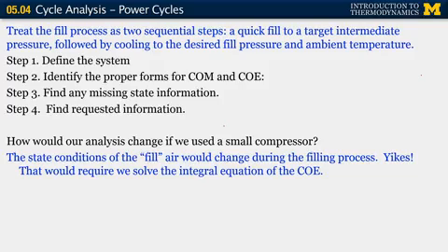Well, as we saw before, this transient analysis is pretty complex when we have steady conditions from our filled chamber. If they're unsteady, the analysis is even more complicated. So let's take a look at the specifics. If we have our conservation of mass equation, recall before we had the change in the mass in the control volume from the initial to the final state given by this expression for the mass flow rate into the system. So what we need to know, again, is how does the mass flow rate vary as a function of time?